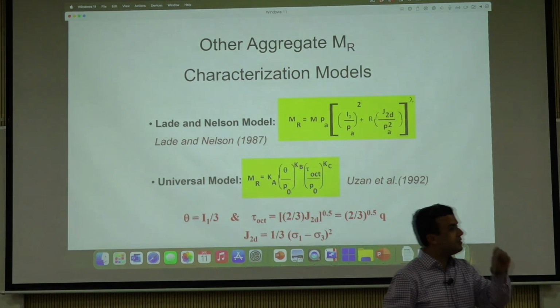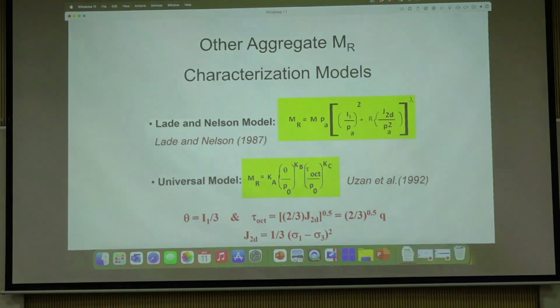No, that is the first stress invariant. I said, what is invariant? An invariant can be a summation or an expression or something, but the point is it does not change with a change in the coordinate system or something like that. Whatever you do, it remains the same. The magnitude does not change, right? So that's what the first stress invariant is.